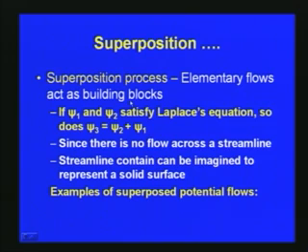So, this is the basic principle of superposition. Since there is no flow across a streamline, the streamlines can be imagined to represent a solid surface. Once the Laplace equation is satisfied with respect to two stream functions, then their combination, whether adding or deducting, also satisfies the Laplace equation. That is the basic principle upon which we are doing the superposition process.